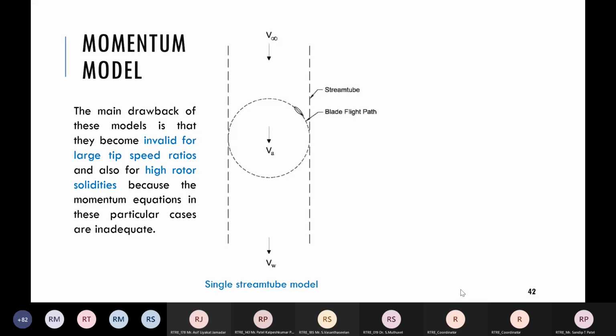So conservation of axial momentum is applied over here, and stream-wise drag is calculated. As we saw in 1D momentum theory, we put a disk on a horizontal axis wind turbine. Here, instead of that, we are considering the rotor as a surface of an imaginary body of revolution.